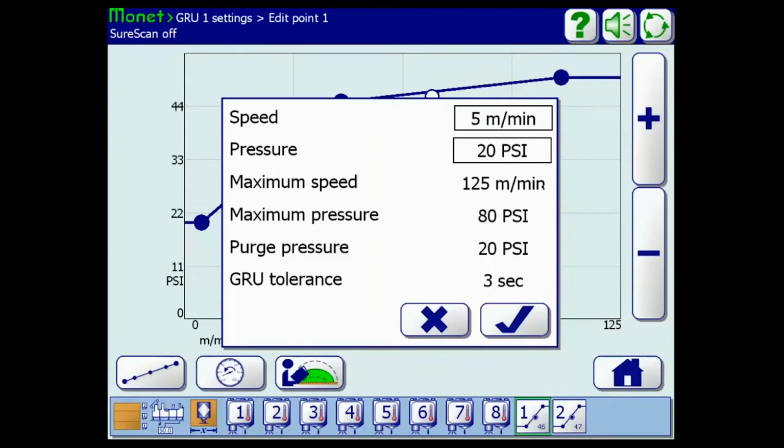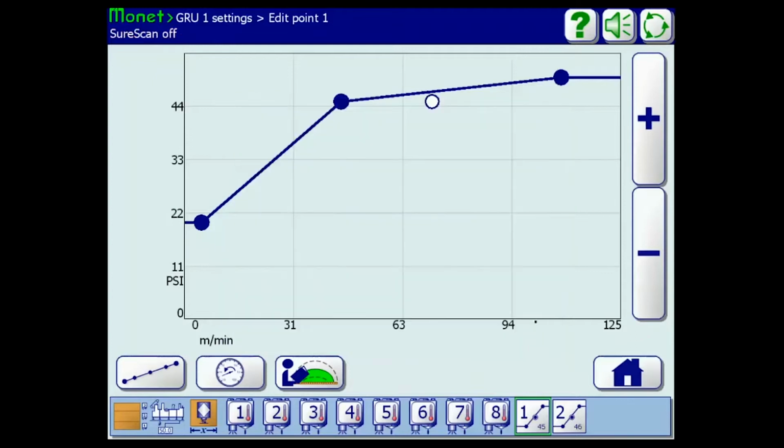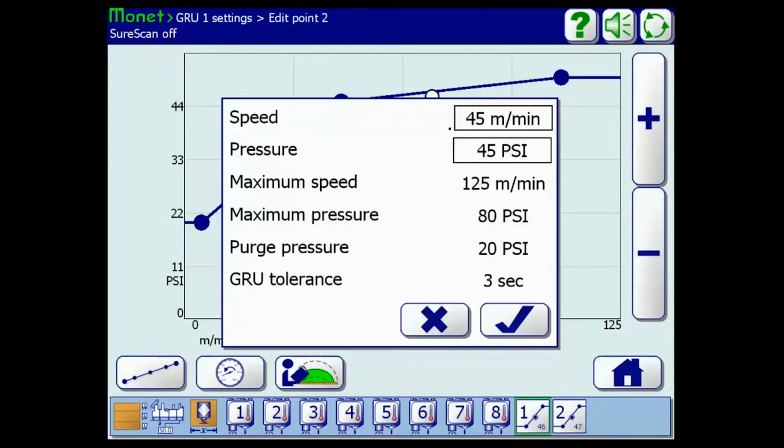The tank itself is approximately a 14.5 to 1 ratio. Okay. So what you see here is actually the 0 to 80 PSI maximum. That's why it says maximum pressure 80 PSI, because that's the maximum amount of air pressure we allow to feed the pump inside the hot melt tank. All right. Obviously, more pressure means more glue. You can manipulate these set points however you wish.